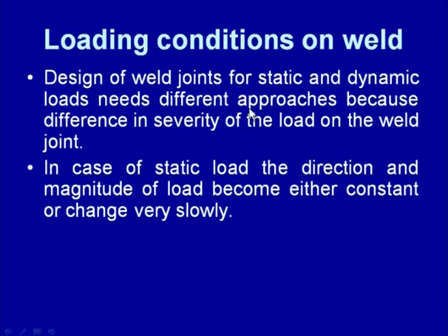For a given weld joint, the severity of the loading can be different for static and dynamic conditions. With a given kind of stress raiser in the weld joint, if the joint is subjected to static loading, then the severity of the stress raiser will not be as high as it can be in case of dynamic loading.